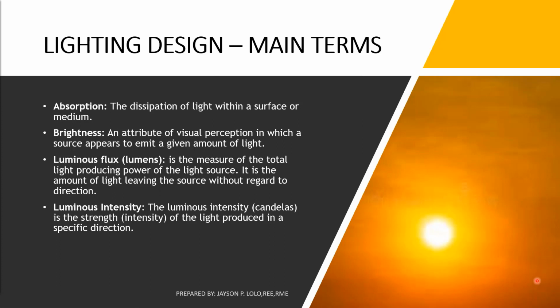Before we proceed, I forgot that the luminous intensity of an optical system is compiled graphically into diagrams known as candela or candle power distribution curves. Sometimes there's a certain way that you can show the possible light shape of a lamp. You can assume that the light shape of the lamp is a circle. Sometimes it is a flower shape, an oblong shape, and there's a luminous intensity table.